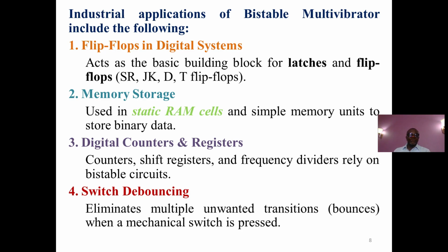They are also used in switch debouncing, where you need to eliminate multiple unwanted transitions or bounces when you are using mechanical switches. Like in your computers, if you press any key, there is the tendency that the spring supporting the key will bounce back and may cause multiple touches.